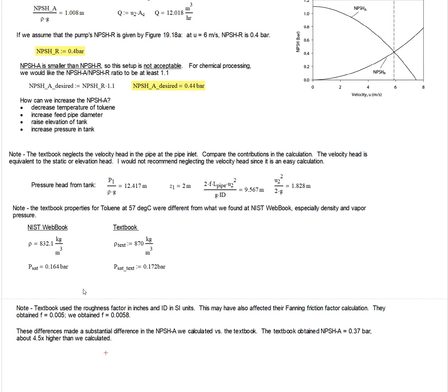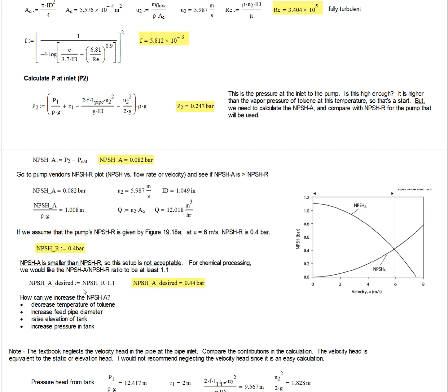So anyway, be careful as you do these problems, and also be careful when you do these NPSH calculations. We're not just looking at the pressures. We have to combine that with what our actual pump is rated for, and so we need to be able to read these pump performance curves and then make our decisions based on what we've calculated, hopefully using all good assumptions and good properties.